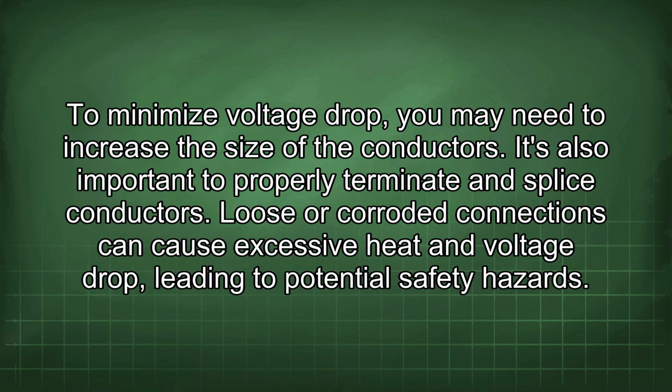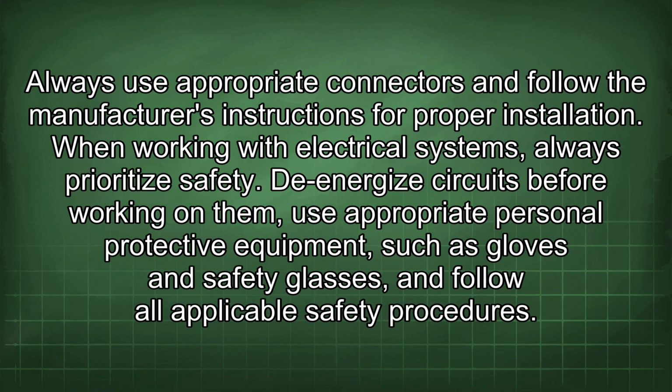It's also important to properly terminate and splice conductors. Loose or corroded connections can cause excessive heat and voltage drop, leading to potential safety hazards. Always use appropriate connectors and follow the manufacturer's instructions for proper installation.